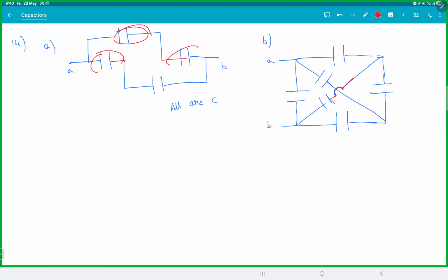This by this is this by this. You can remove that CD in the middle. Anyways, now if I try to use the nodal analysis, you'll notice something. This is A, this is B, this is C, this is D. Now this is the big clue, okay? If all the points are different and if you redraw the circuit, you're not going to get anything, isn't it? Nodal analysis is pretty useful if you have at least one common point. If you just have all the points different and if you redraw, you're not going to get anything.